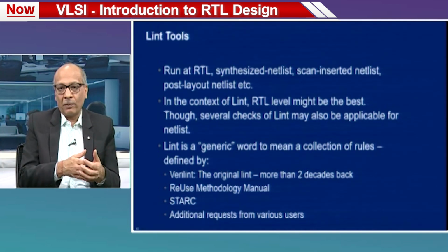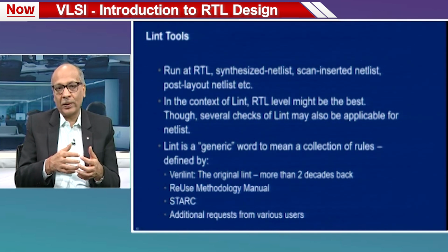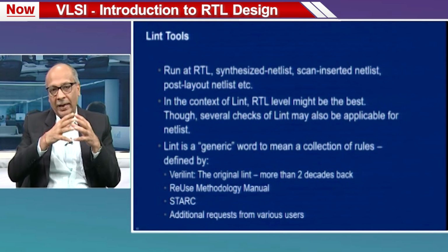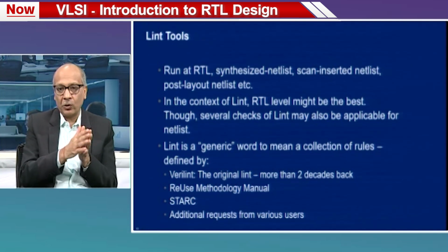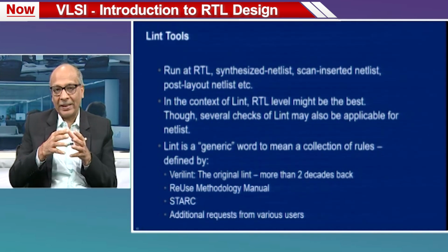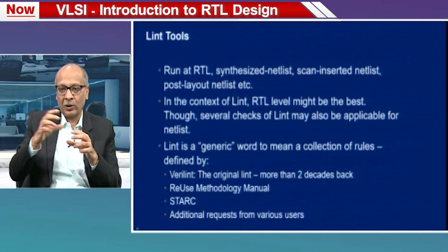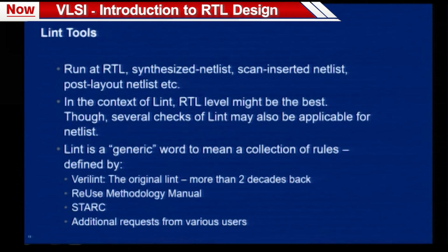Then there was a book published called Reuse Methodology Manual. Again, it talked about multiple coding guidelines which said that if you follow these coding guidelines, it will be easy for the designs to be maintained and reused. You created one block, I can use this block in another block. So, all the coding guidelines from that Reuse Methodology Manual came into lint.